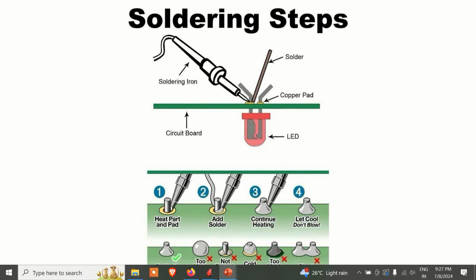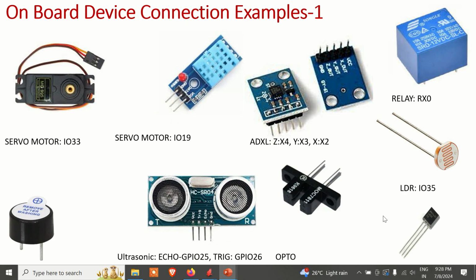That is proper soldering. Otherwise it may lead to dry solder, or it may spill onto nearby pads, or it may end up in unwanted shapes.